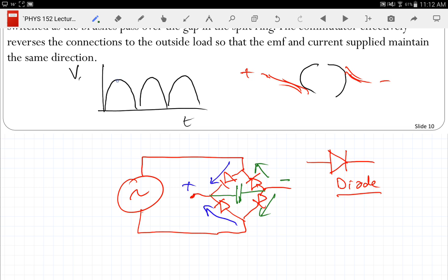So with this design, your voltage pattern would look like that green pattern. So it's better regulated. And I'm guessing those of you that have taken the circuits class have studied how to make a well-regulated power supply? Kind of. What you really do in real life is you get a voltage regulator chip that has things like a Zener diode in there that will cap it. You can make very well-regulated DC voltages from this. Those are the methods.